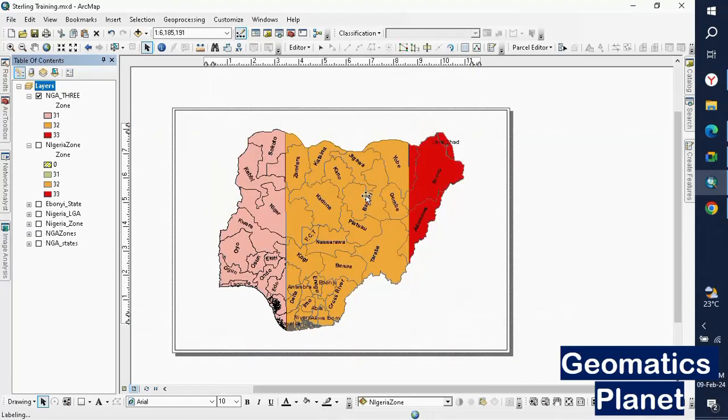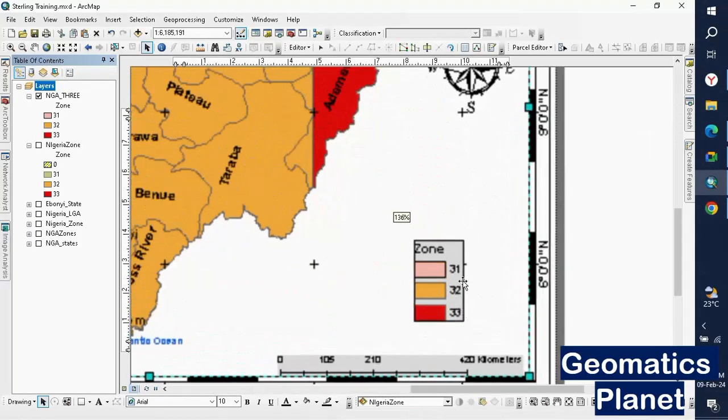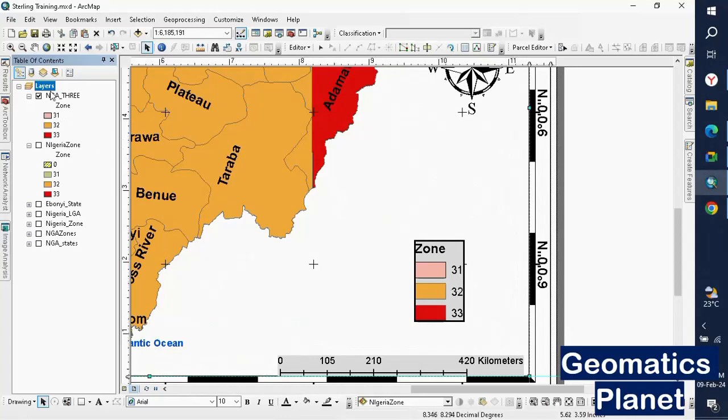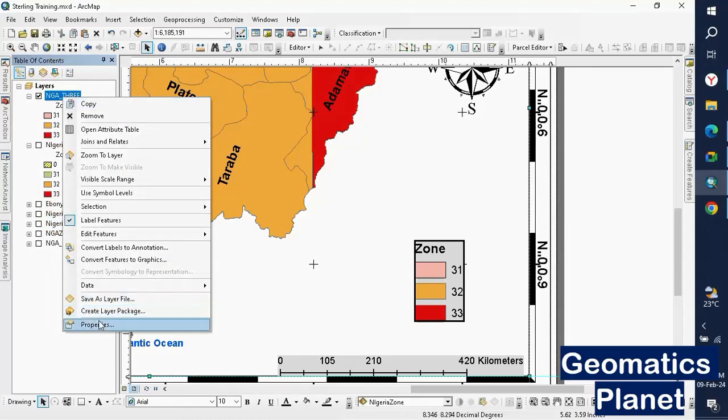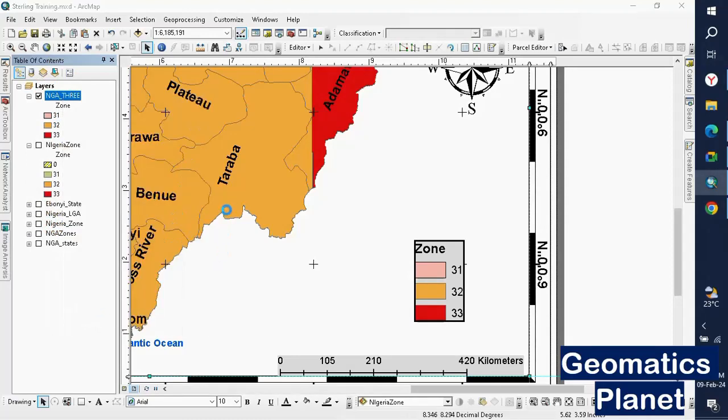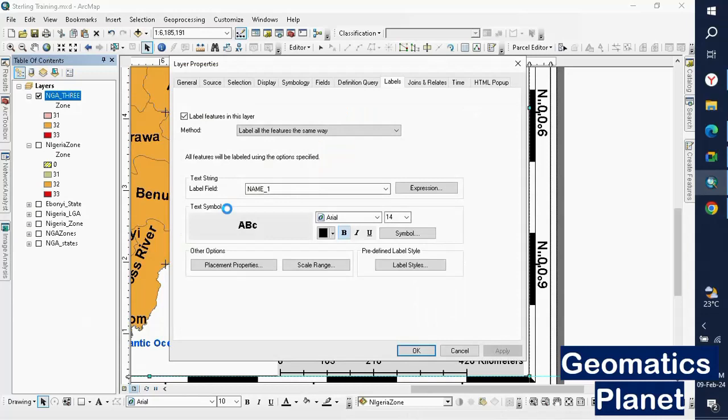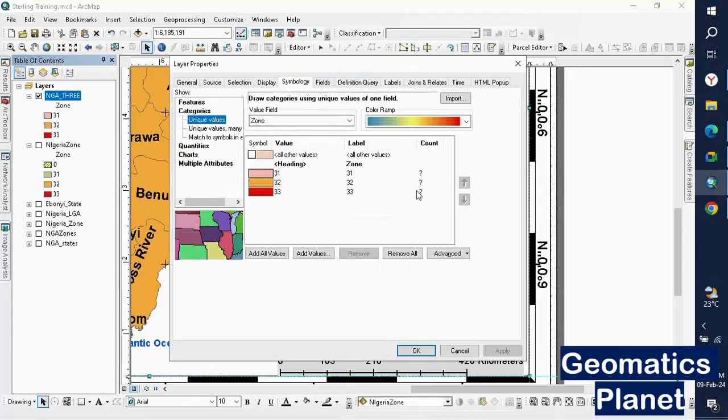You write the name of it, and then go down here like you see it. Make sure it is like mine. The reason I am saying it should be like mine is because I just want you to follow what I did. So this part is just putting it to look the way it's supposed to be. Go to the symbology tab here, come here and type UTM zone 31 north, because that is where we are. So you put it UTM zone 31 north.